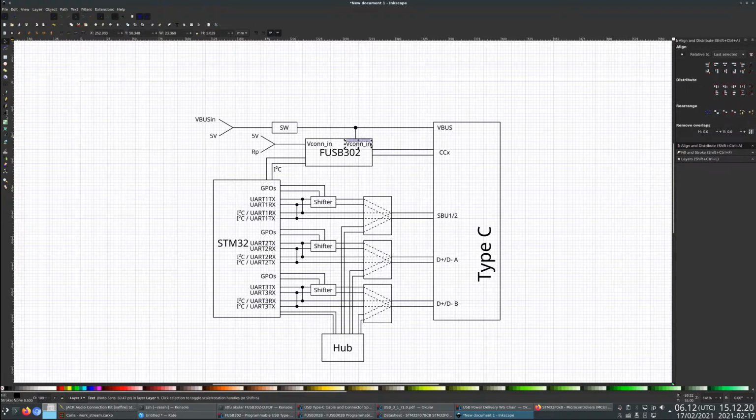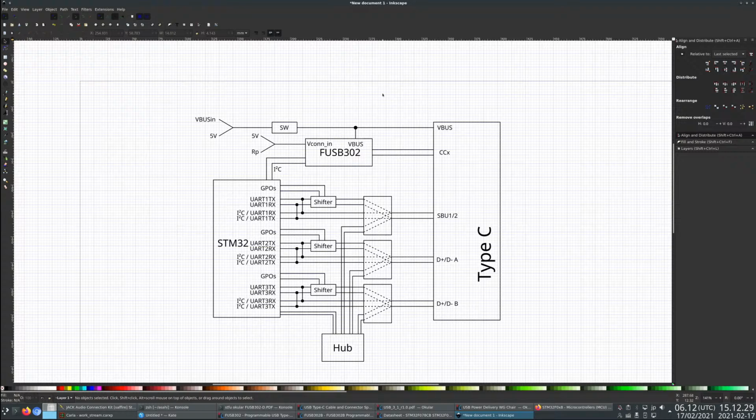Basically, this is the VBus on these chips, by the way, on the FUSB is just a measurement input. It doesn't actually switch anything. So this means we can use the following modes. Yeah, the VBus switch needs to be able to tolerate 20 volts on this side, while this is still 5 volts. One option would be to just say, if you want to use this as a sink, leave this jumper disconnected. But ideally, we want to not rely on people not forgetting to remove a jumper for this to not explode. However, since this is only used for driving, another thing we could do is just have a diode in here. And there would be some voltage drop here, but it would probably work for most applications.